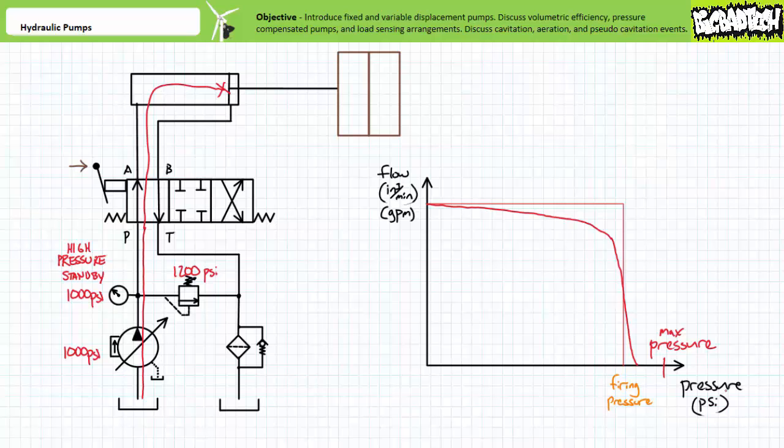While the molded piece cures, the cylinder must maintain constant extension force, otherwise the final product would be damaged. Yes, in a perfect world, one could theoretically shift the directional control valve back to the closed center position and lock the actuator in place. But the real world must take into account both leakage across the piston seals and the limited sealing ability of the spool in the directional control valve. This is where the knee and tail regions of the pressure-compensated variable displacement pump come into play.